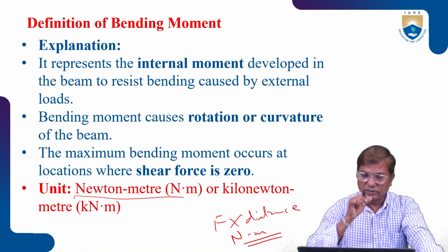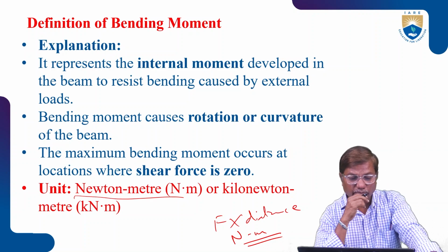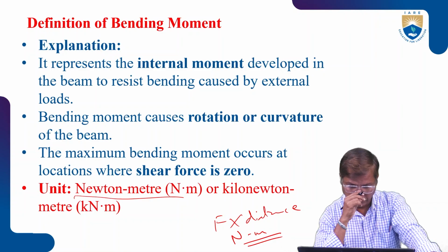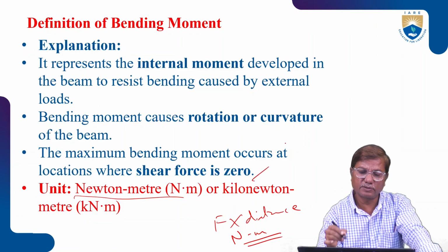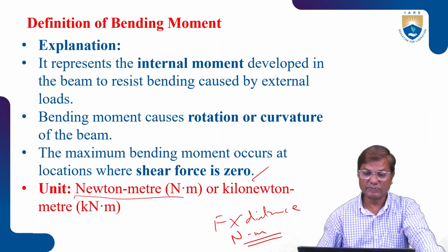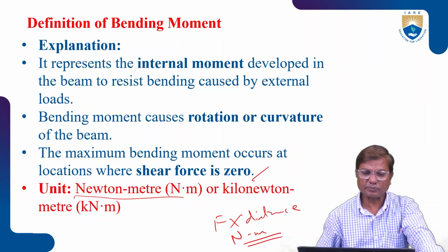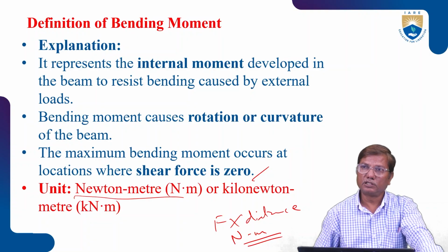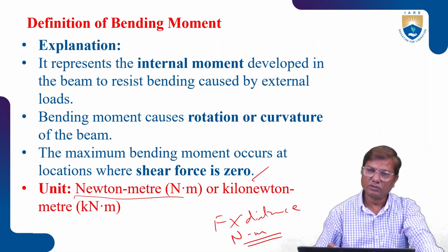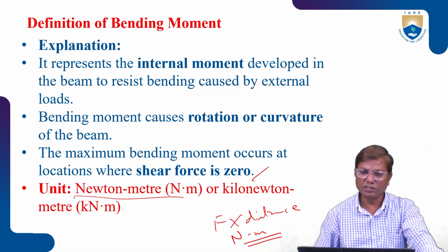And at the point of zero shear, you will have the maximum bending moment. In other words, where the shear force changes sign, we will have maximum bending moment at that point.